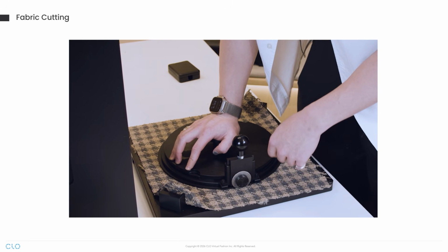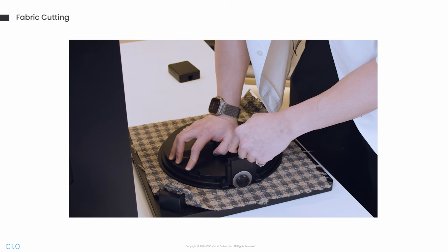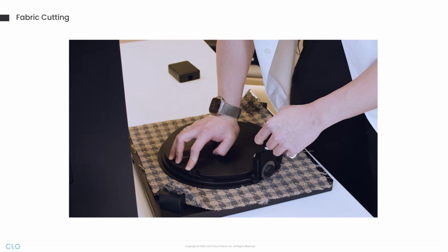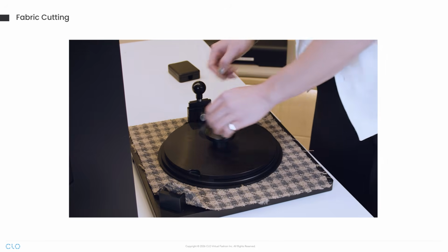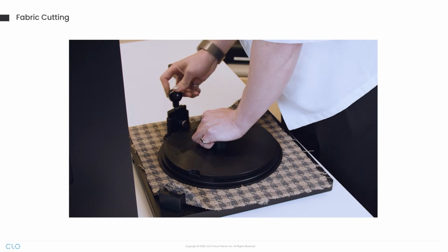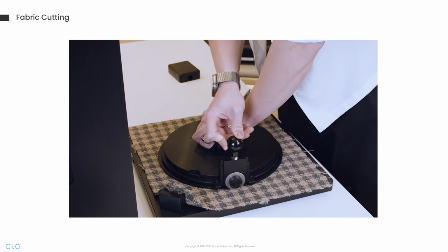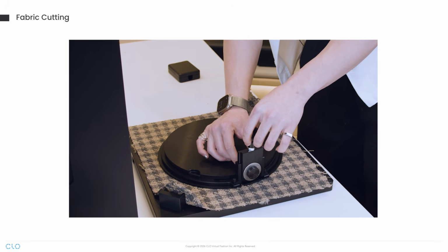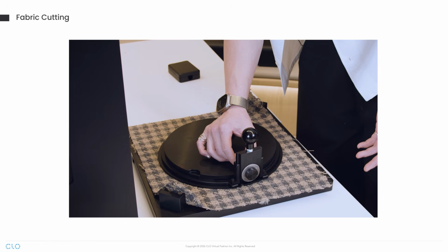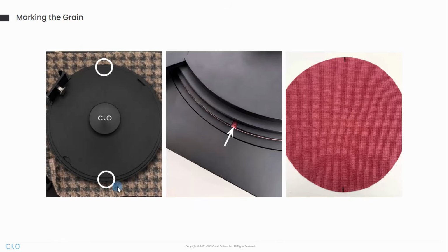With one hand, press down gently on the handle at the center of the circular plate to keep it from shifting or moving during cutting. With the other hand, hold the blade handle and cut the fabric by smoothly rotating it along the outer edge of the circular plate. Rather than applying excessive force, roll the blade with light pressure, repeating several times. Applying too much force may damage the blade unit or bend the blade, resulting in size errors in the sample, so please be especially careful.